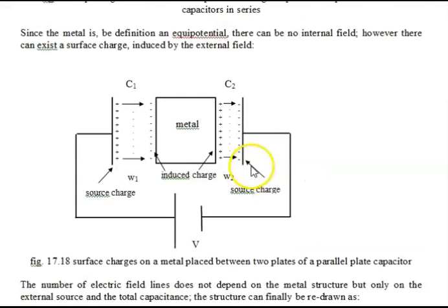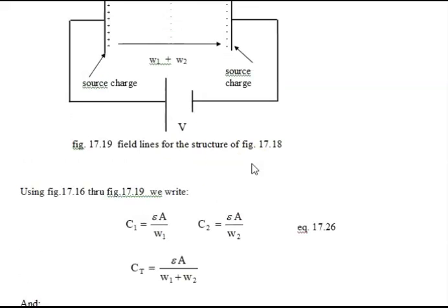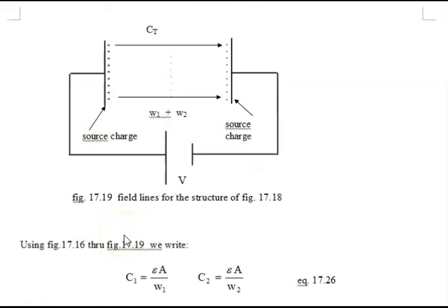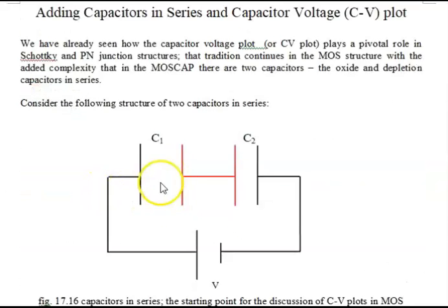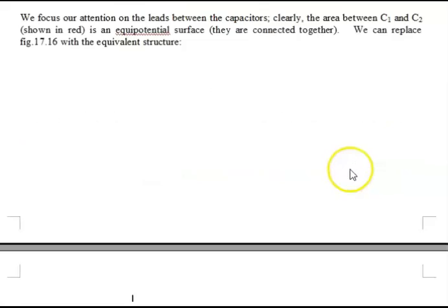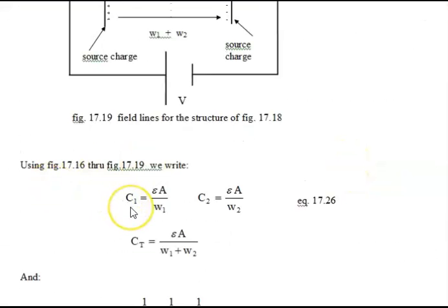So now we've got everything we need. And we just say that the capacitance C1, which is the capacitance here, sorry to go back and forth, this is C1 and this is C2. We can write those capacitances out. And then again, these are not areal capacitances because in a CV plot we actually measure capacitance. So we stick the cross-sectional area in.